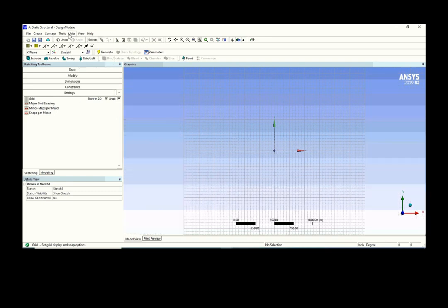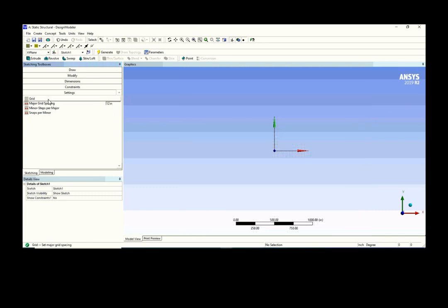If you go to Units here, choose inch, so everything is in inch now, right? Here I want to set the major grid to 12 inches, because I want each major grid to be 1 foot. For us to draw, we have 3 feet, right? So we draw it in 1 foot units. The minor is also 12. Wait, why doesn't it come up?